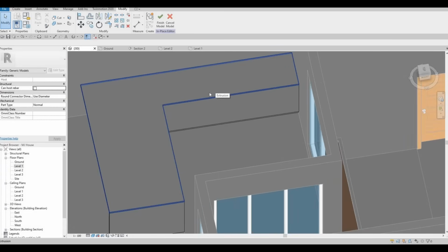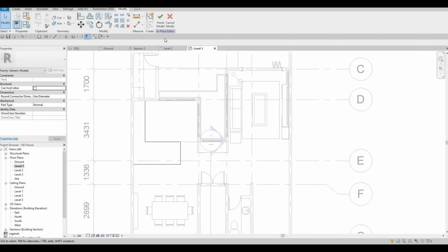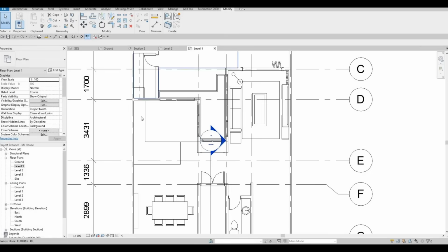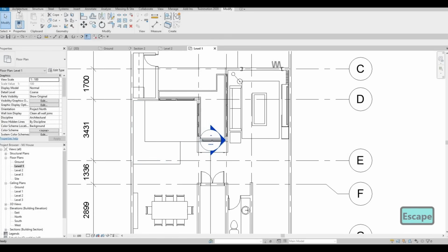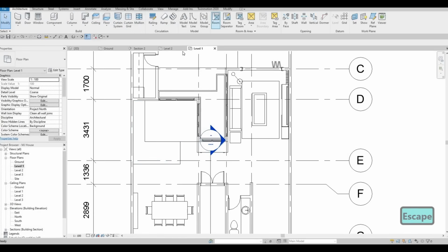And then we could add or create the cabinet doors, but before we do that, we need to add in where we could add in the faucets or the sinks. So let's click on finish first, because we need to void those. So we need to add it first, and then we need to void it again.